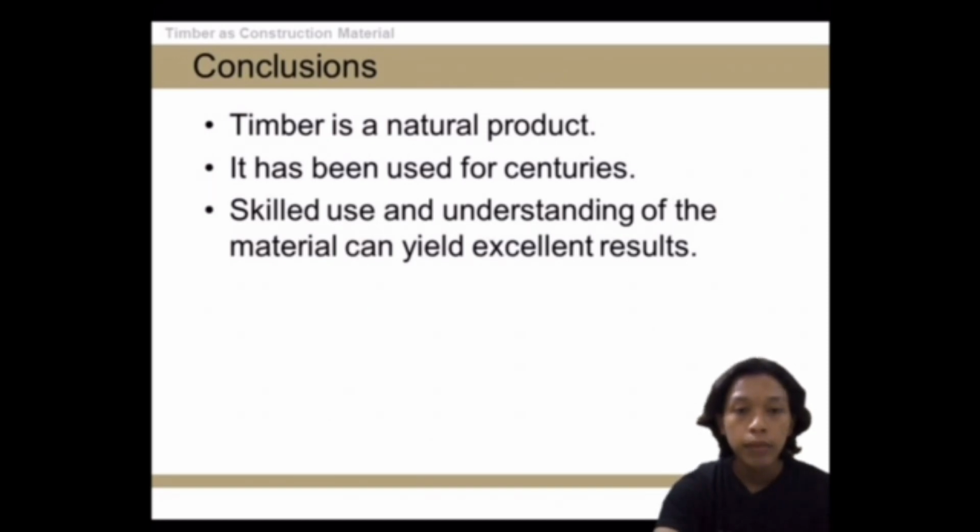However, if the bound moisture in the wood cell walls also dries without some control, the fibers contract and shrinkage occurs. Conversely, if dry wood is allowed to absorb moisture, then the reverse of this process occurs, creating dimensional increase and distortion.